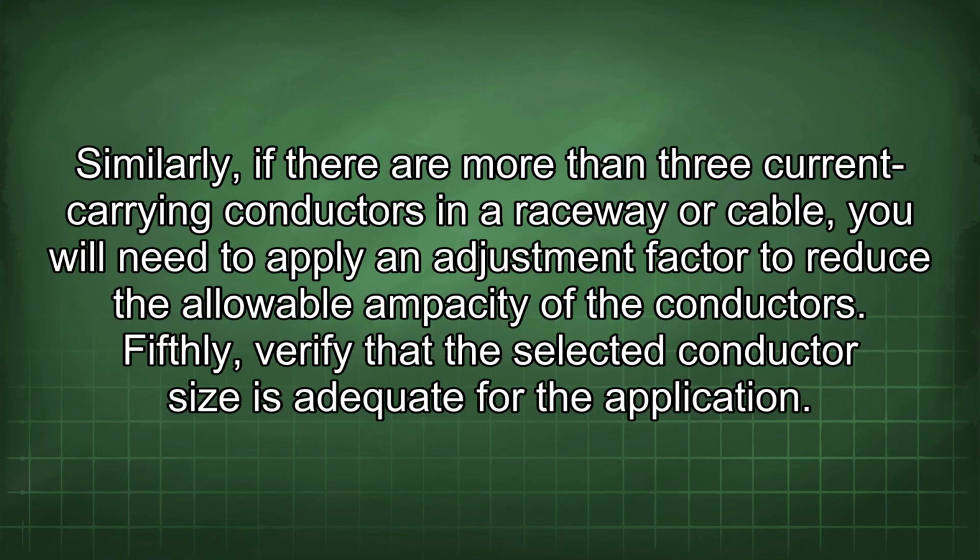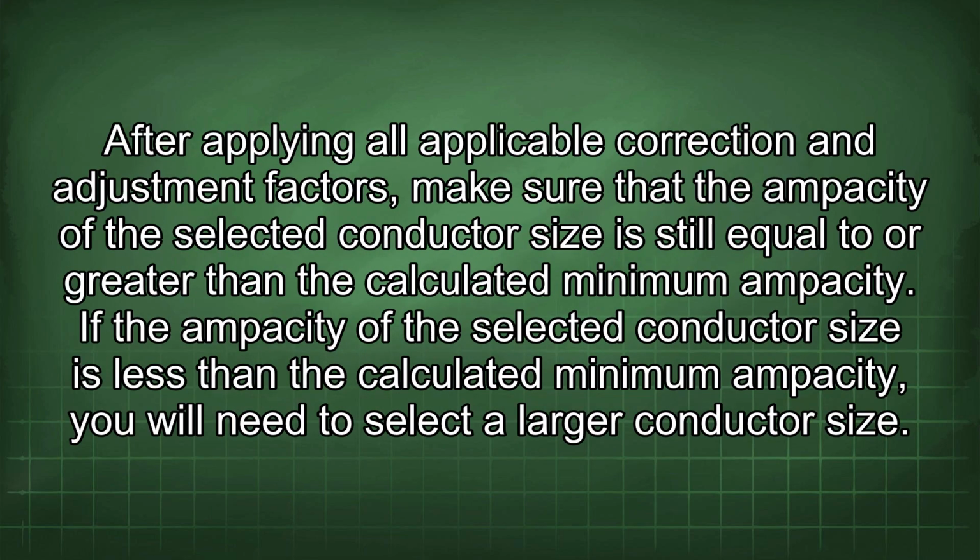Fifthly, verify that the selected conductor size is adequate for the application. After applying all applicable correction and adjustment factors, make sure that the ampacity of the selected conductor size is still equal to or greater than the calculated minimum ampacity. If the ampacity of the selected conductor size is less than the calculated minimum ampacity, you will need to select